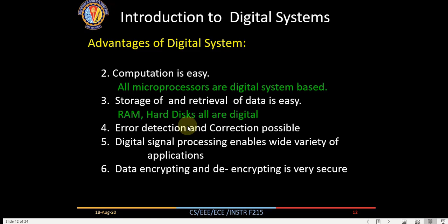So if I have to transmit 1000, then I will add a fifth bit. The fifth bit will be 0, so that the total is odd. So that is known as an odd parity. Okay, I'll send it to Manish. So Manish, once he receives the signal, will see that there are 5 bits, the fifth one is my error detection code, and he will see that the total is an odd number. That means there is no error.